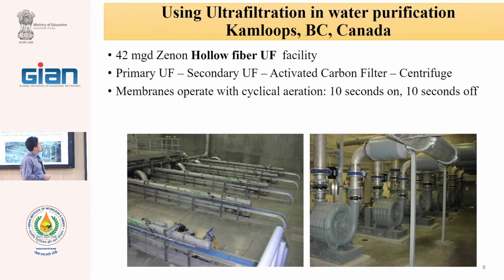And after UF, this activated carbon filter is used for adsorption of the small molecules, and also activated carbon can adsorb the iron. It can adsorb a low amount of heavy metals. Therefore, it can be used.